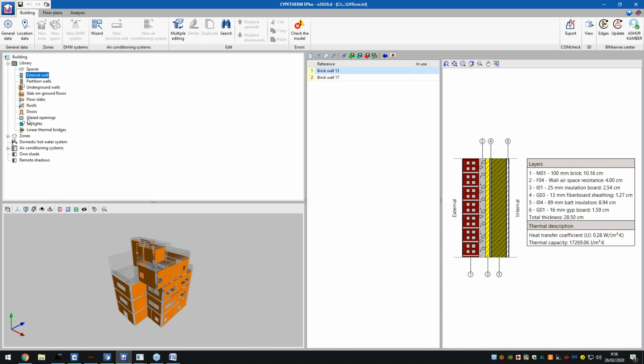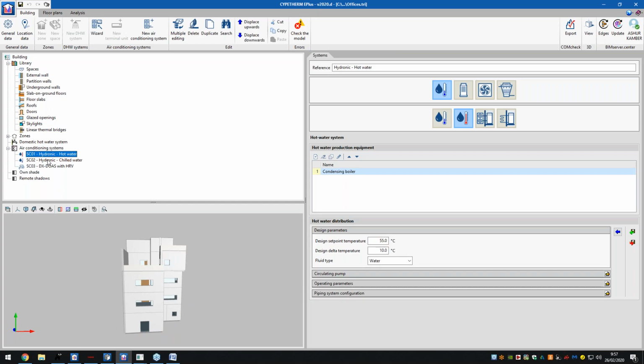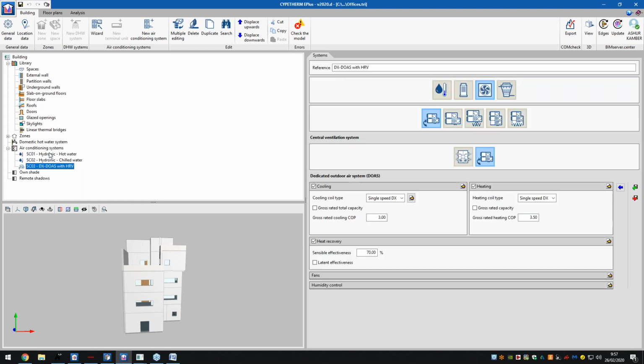Now, what I want to mention prior is how do we connect our HVAC installations with our energy? Well, if I come over here, you can see I've imported the same project. The program automatically understands that I have air conditioning systems within the project. So you can see all my different hot water hydronic and chilled water hydronics, and also my HRV installation. And I'm able to make specifications there and detail those types of equipment, not only in our HVAC installation, but also in our E+ installation.